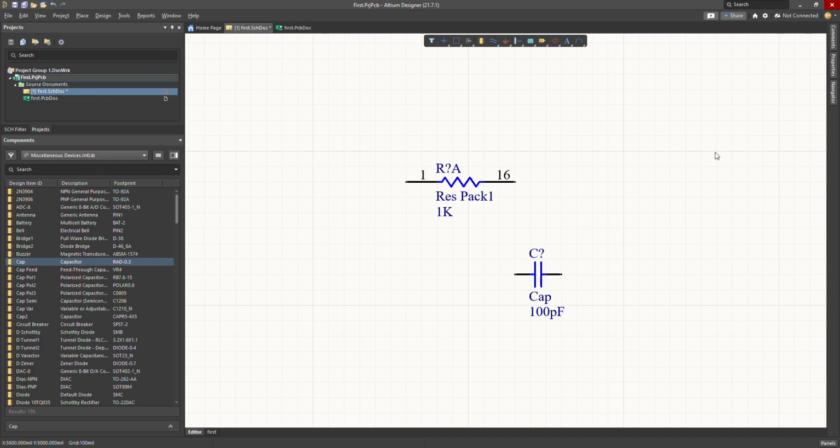Another thing to mention in Altium, if you drag from right to left, it doesn't matter if it's up to down or down to up, as long as it's right to left, you can see the border of the selection is green. Green means if part of the component that you're selecting is in the area of the selection, the part will be selected.